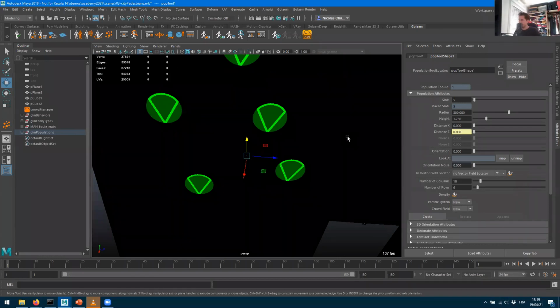And the thing is, if you stay with the meters units, you'll have to multiply every single parameter, which depends on distance, acceleration, or speed yourself. And that's probably a lot of parameters. And if you miss one, you'll have some really weird behaviors. So it looks like meters is not exactly the right answer.